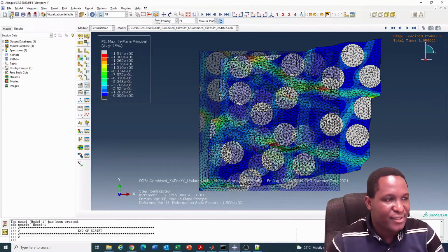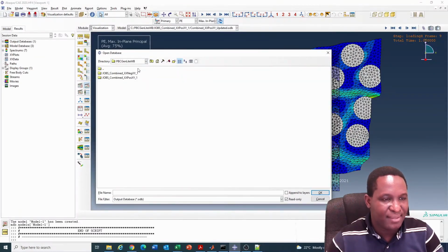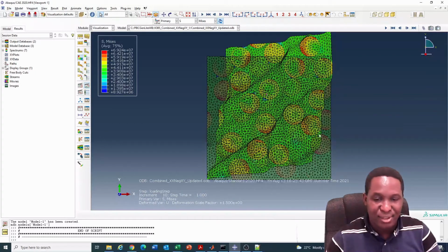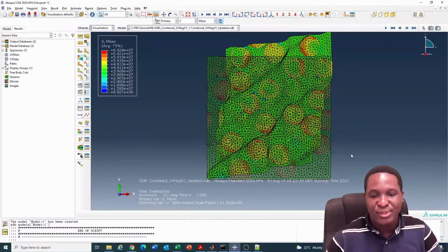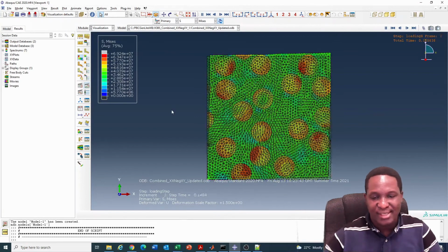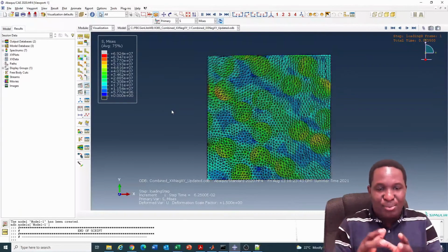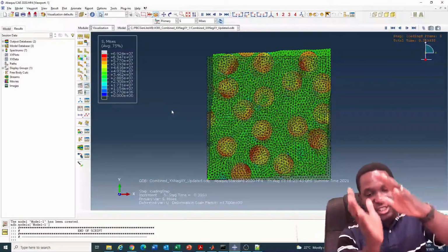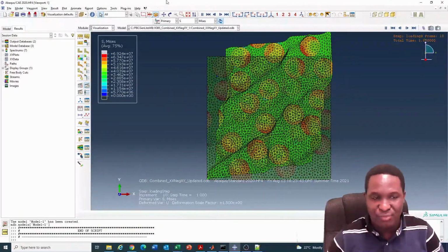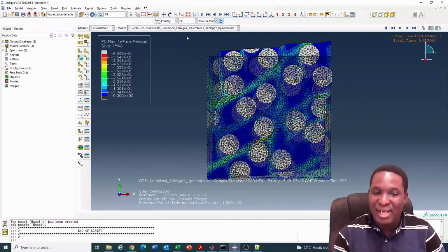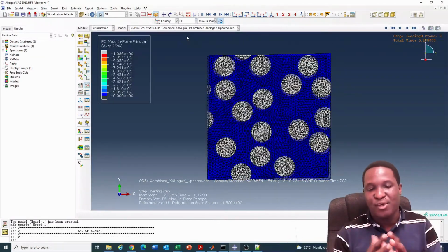So what of the second case? So again, we navigate back to the negative case, look at the result. Now in this case it's different because it's no more pulling out. So what you could see is that the front end is being pushed. So if we animate that, you could see it starts up and you're pushing in the front end to create this compressive loading, as well as the normal shear load that you're generating as well. So clearly those two simulations are different. One is a tensile pull, the other one is a compressive push.